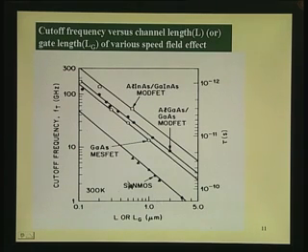Now, you can see if I have an alternate material, we will see how it is later on, but you can see in this graph, all these open circles, the cutoff frequencies are higher than silicon. For example, you can see what you get with 1 micron with this gallium arsenide based field effect transistor, that is something like 10 to 15 gigahertz range. I am sorry, gigahertz, megahertz nobody talks of these days.